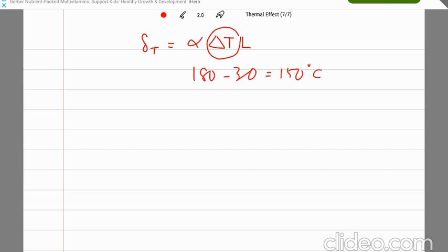So you have the value of alpha, and also L, and putting them into this formula you will get the deformation of CD caused by the temperature increase. Okay, so you will see that CD actually elongates more than the existing gap, which is more than 0.7 mm. So definitely it will.